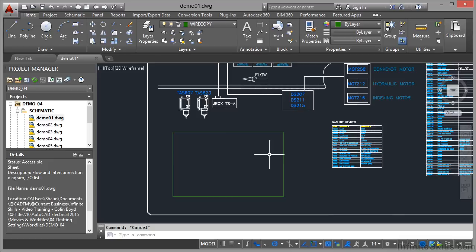But it's a very useful tool in AutoCAD Electrical because I can guarantee you'll have wires, panels, junction boxes, and sometimes have lines or polylines underneath them that you might not need. So you can utilize selection cycling to tidy up your AutoCAD Electrical drawings.